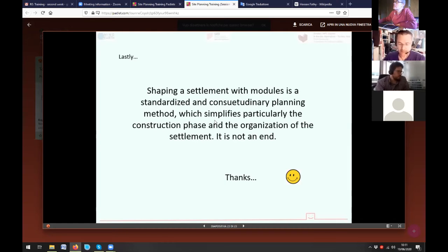And we also need to take into consideration the sensitivity of gender, because you know the latrines for women. If you put latrines for women and latrines for men in the same location, it will be sensitive for the women or girls to use the latrine. And if you put them in the public space or in the center, it will be seen from the other side. All of them can look at these women coming to the latrine.